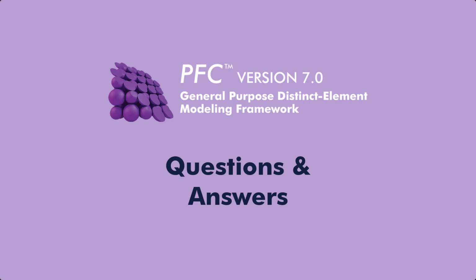Sure. And maybe I didn't quite say calibration correctly. Calibration is not needed for the elastic response. So for the target Young's modulus and Poisson ratio, calibration is required for strength, right? And for a failure response, as it is in 3DEC and in other models. So I maybe didn't say that or highlight that quite correctly. Why is calibration for elastic properties not required?